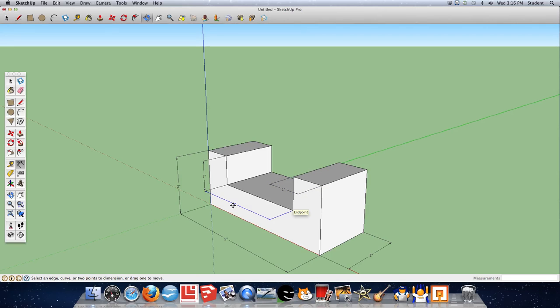Now, I've doubled up on critical information. I could just delete this dimension here, because the understanding is, if this is 3 inches on center and my object's 5, I'm going to have an inch here and an inch here. Otherwise, guys, that's fantastic. Very simple to use.